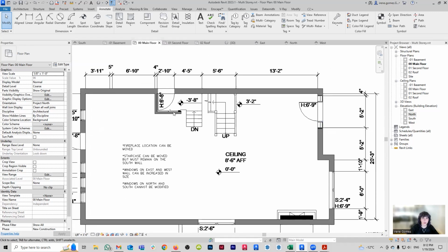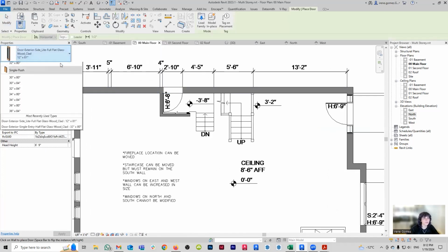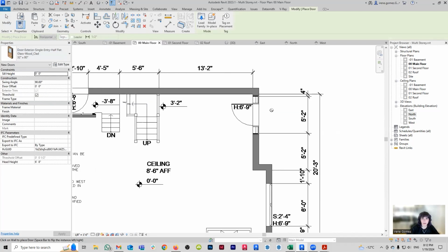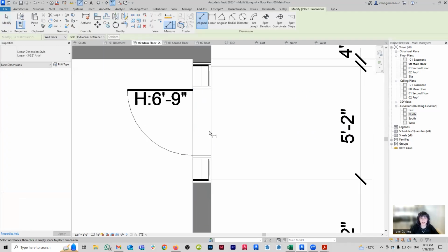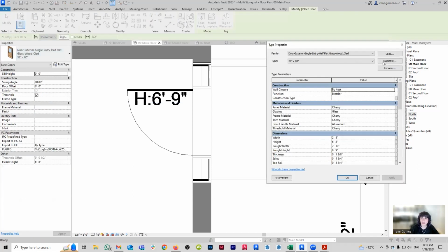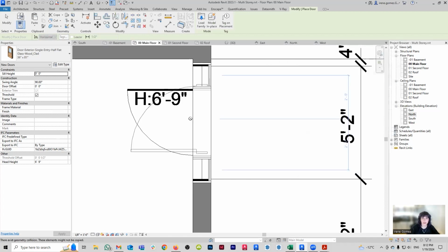And now I'm going to be duplicating this door. So I'm going to use the same guy, but this guy here is the width the same? No, it's actually bigger. I'm going to measure my door opening. It's 3 feet, so door, edit, duplicate. This guy's going to be 36 by 81. And then I'm going to delete this. 36 by 81, 36 by 81. How uninspiring. And then I'm going to put my door here, space to flip it.